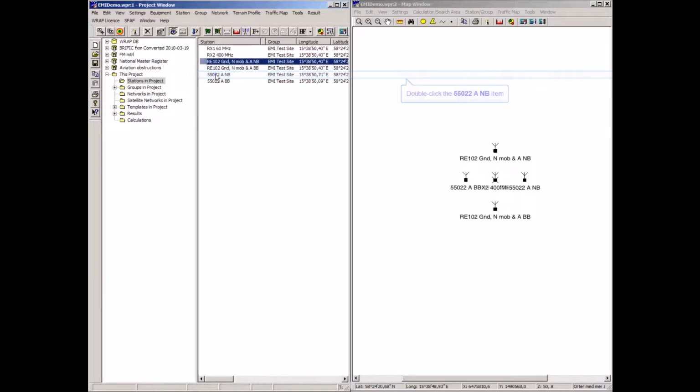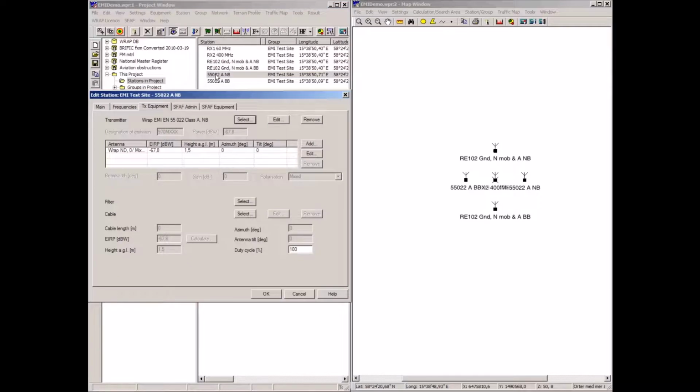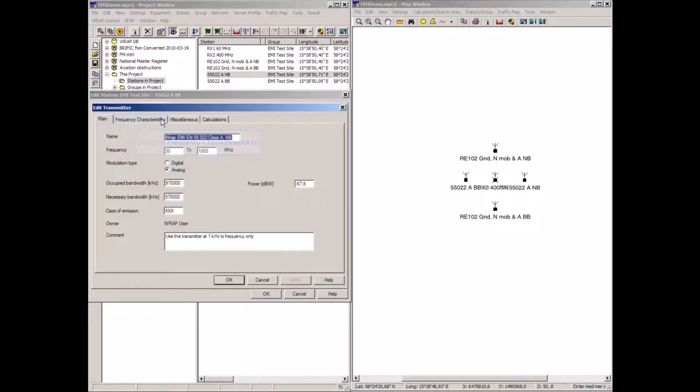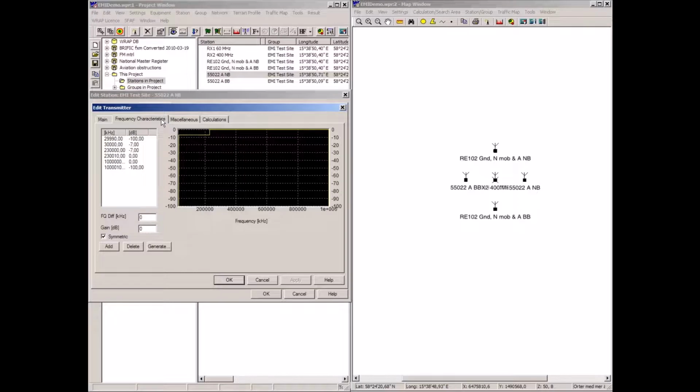These two are European civilian standards according to EMI reference standard EN 55022, Class A narrowband. These look like this, and that step may be that at that frequency, the reference bandwidth, the measurement bandwidth for the standard is changed.